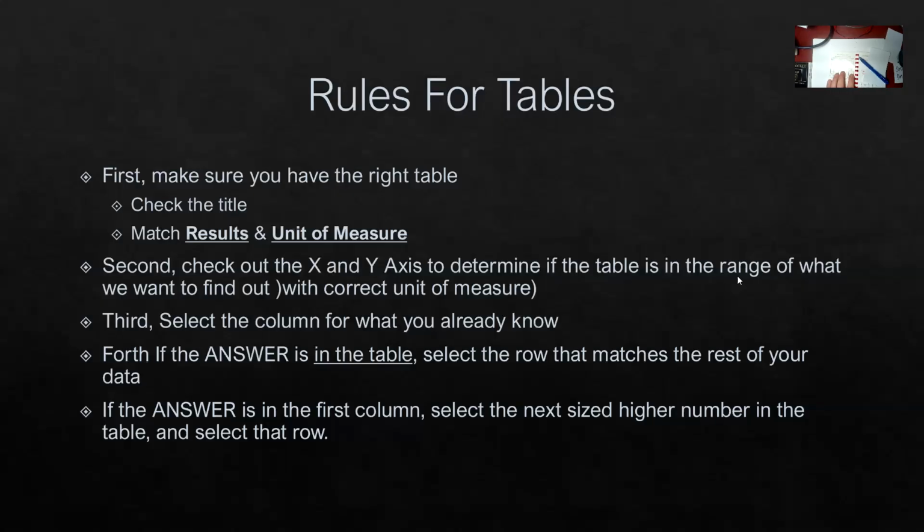Sometimes you have to round up. Rounding up is most common. For instance, I don't want to round down when choosing a wire size. If I've got an amp requirement that might be 25 amps, but the nearest wire size is one size larger, then I have to choose the larger wire. If I choose the smaller wire, I will potentially burn it out.